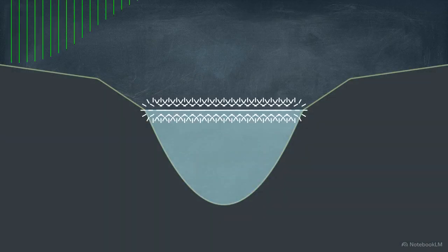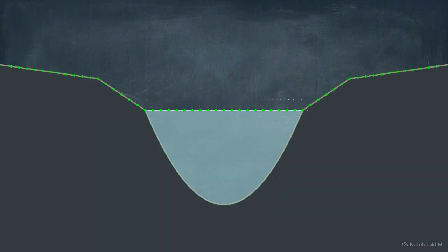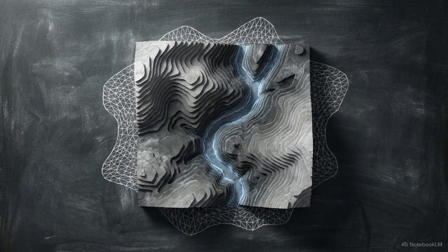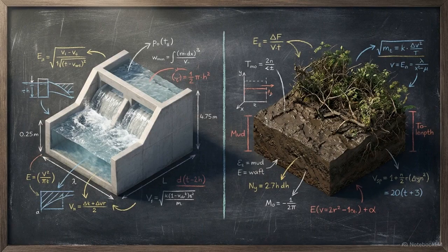Both drones and aerial LiDAR suffer from a second topographical blind spot. They cannot penetrate the water's surface, which renders riverbeds artificially flat in the data. We fix this by surveying the river with sonar echo sounders and splicing that underwater bathymetric data directly into the terrain cross-sections. Fusing canopy-penetrating LiDAR with underwater bathymetry provides the physics engine with accurate channel capacity and an objective topographical truth. Topography dictates where the water flows, but the texture of the surface dictates how fast it gets there.